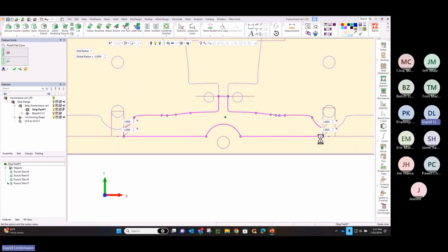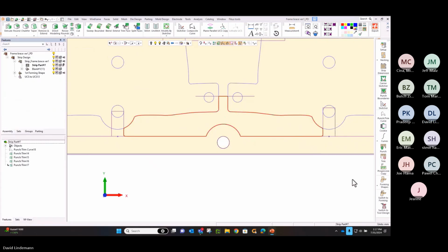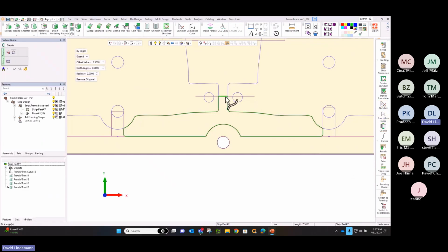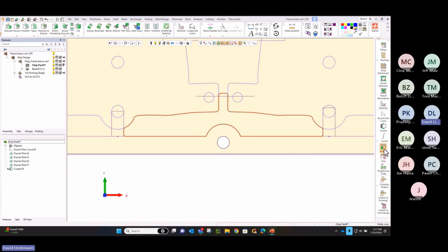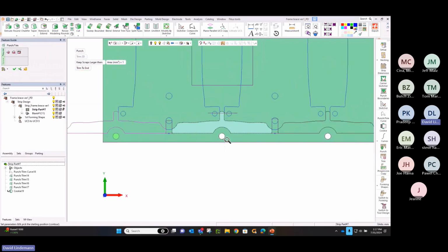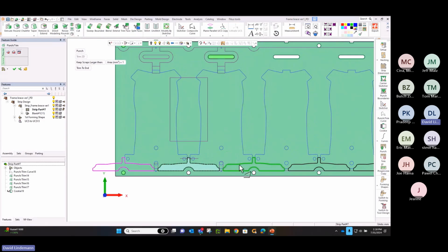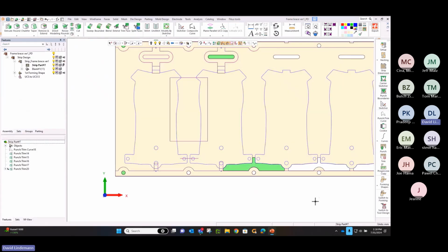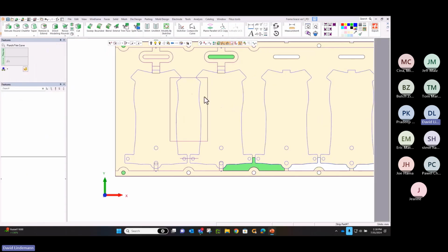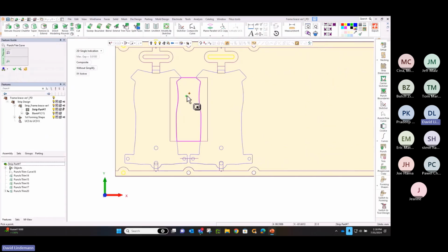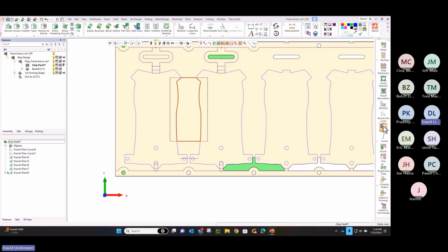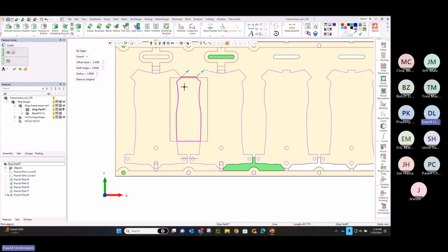Tweak this a bit by rounding the corners along the carrier. And then in the middle, I've got this area where it's going to overlap onto another punch. So we'll put what we call a cookie. That overlap can be as I've drawn it, or it could simply be something with an extra shear, or a gap, I guess, an overlap with that misplacement, so that I can put something in there to avoid the shear that it might run into.